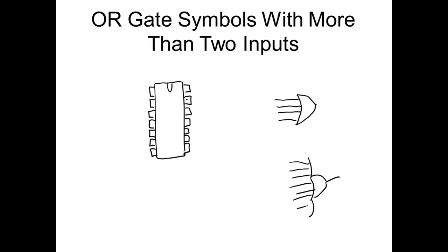Yeah, but what most people forget is that every gate has got to have an output. We got to bring the output out somewhere, right? You understand? So we're going to lose 2. Yeah, we're going to lose 2: one for VCC on the AND gates that we're using, and one for common. So that leaves us 12 pins to work with, right? You understand?